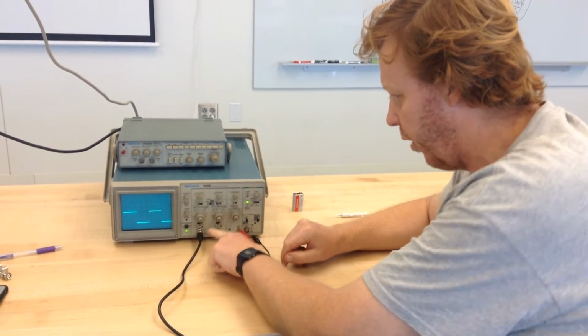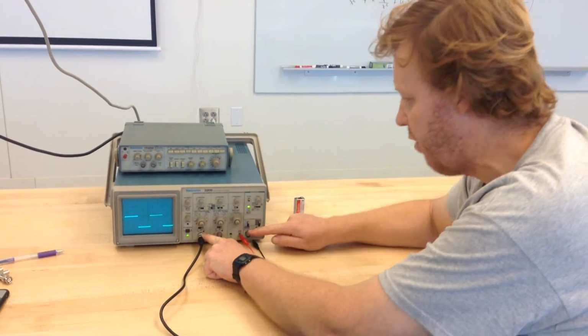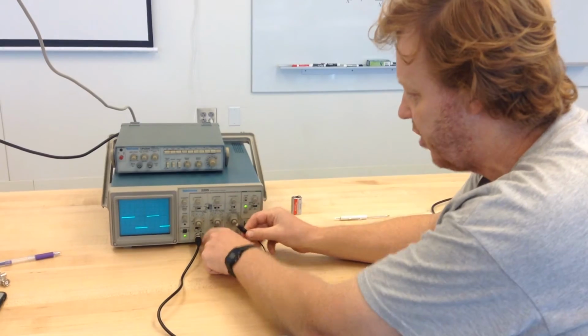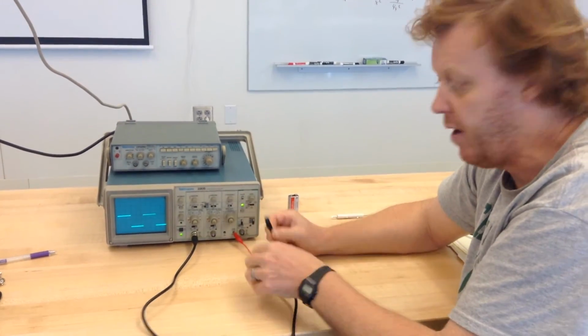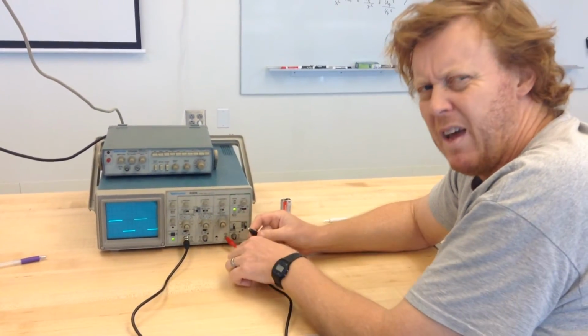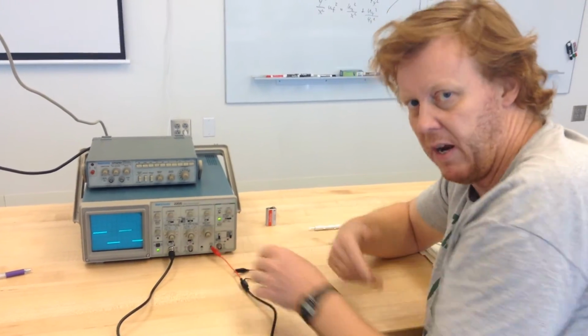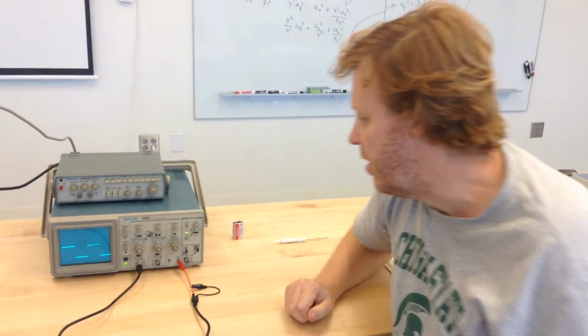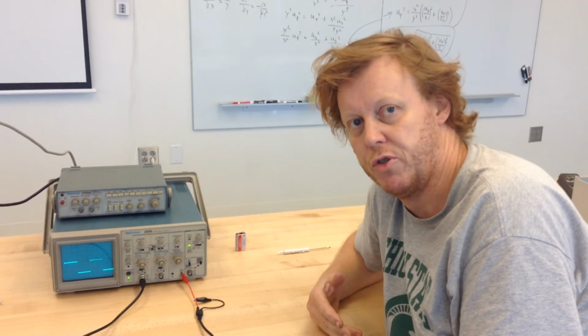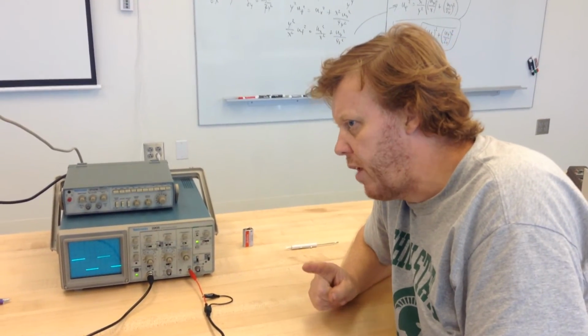So if I got a voltmeter and pull it from here to here, I get 0, or from here to here, I get 0. But this is at the same potential as that because that's just the way these cables are made. So I actually don't need this cable. It's a little bit subtle, but as the months and years go by and you're using these devices, you'll get used to the notions of grounds.